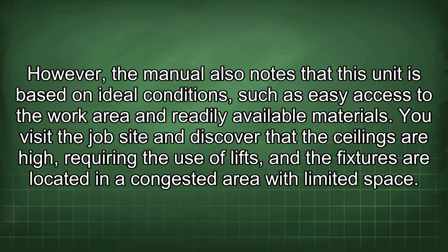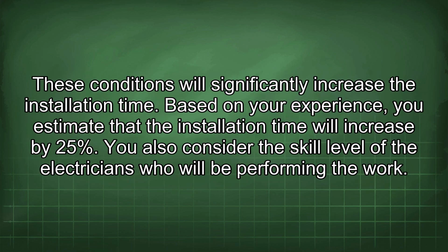However, the manual also notes that this unit is based on ideal conditions, such as easy access to the work area and readily available materials. You visit the job site and discover that the ceilings are high, requiring the use of lifts, and the fixtures are located in a congested area with limited space. These conditions will significantly increase the installation time. Based on your experience, you estimate that the installation time will increase by 25%.